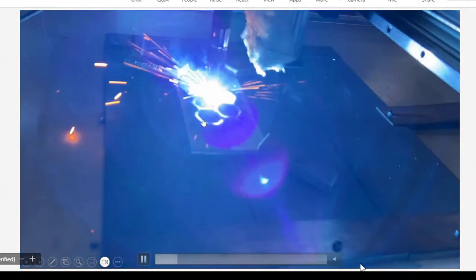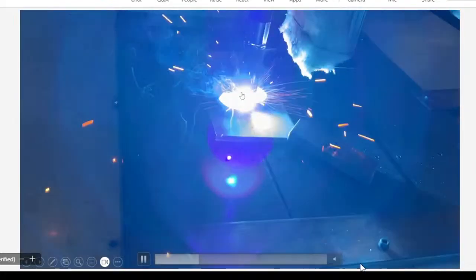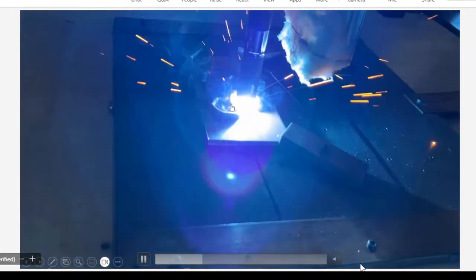At the end of the video, you can see how the toolpath configures itself and makes layers over layers. This hexagon, these auxetic structures I tried, and the finishing is very good. The precision is very good, less than 0.5 mm of precision is there. You can see at the end what I'm trying to say.